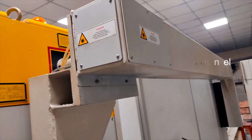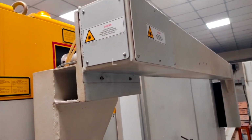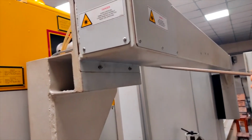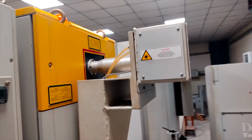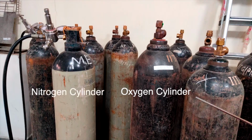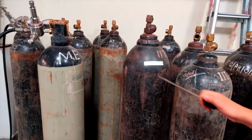These mirrors are highly reflective. This particular beam or box kind of structure which is there on your screen, through which the laser beam will be transmitted to the location. Now we need the assist gas. This black color cylinder is the oxygen cylinder, and the white cylinder with black shoulder is the nitrogen cylinder. Oxygen we will be using for the assist gas. This is nitrogen gas, as I mentioned.